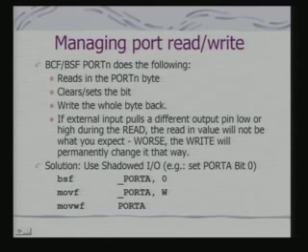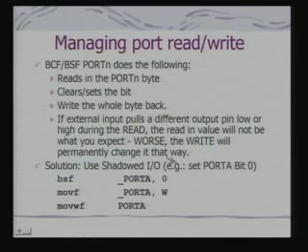So, this also can be a source of problem and a source of error when you are interfacing external devices via port. So, one of the solutions is that you use what is called shadowed I/O. That means in this case basically when I am showing underscore port A, it is not that I am writing onto exactly the port A memory location, but a copy of the port A memory location which is in the general purpose set of registers which PIC provides for.